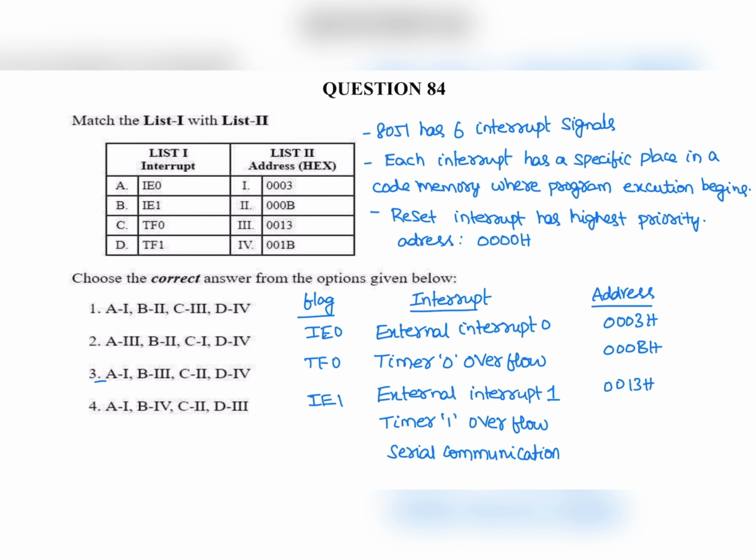0013H. So this is INT0 interrupt, INT1 interrupt. So this is timer 0 interrupt, and this is timer 1 interrupt, and the address is 001BH. So whose flag is TF1. So the flag here is RI/TI. The address of this interrupt is 0023H. Interrupt vector address is 0023H, and it is serial interrupt. So these are the various interrupts in 8051 microcontroller.